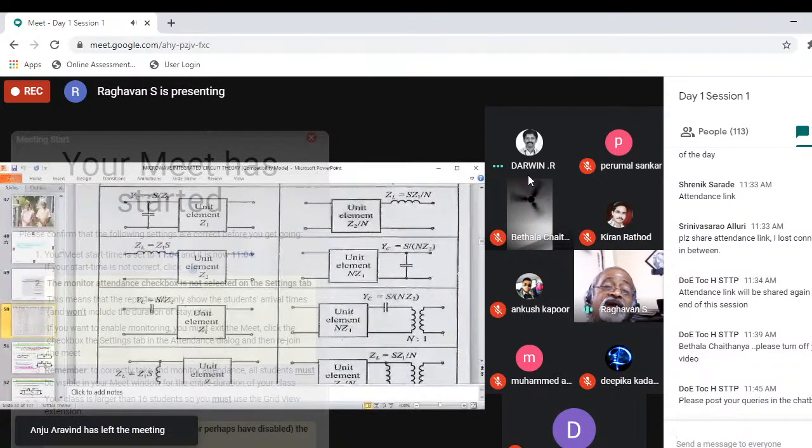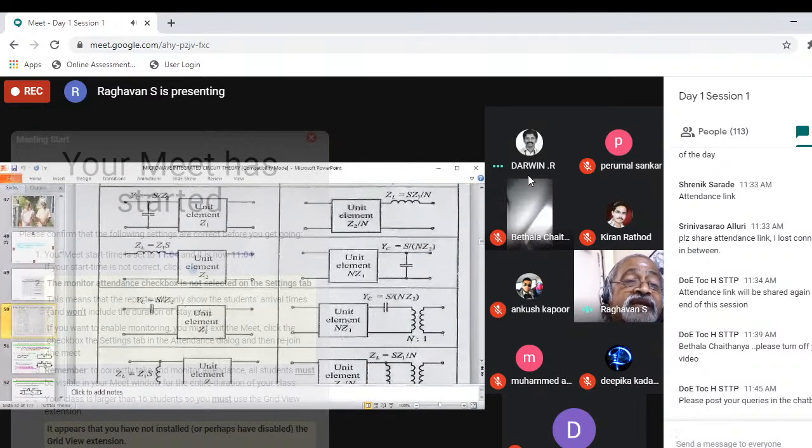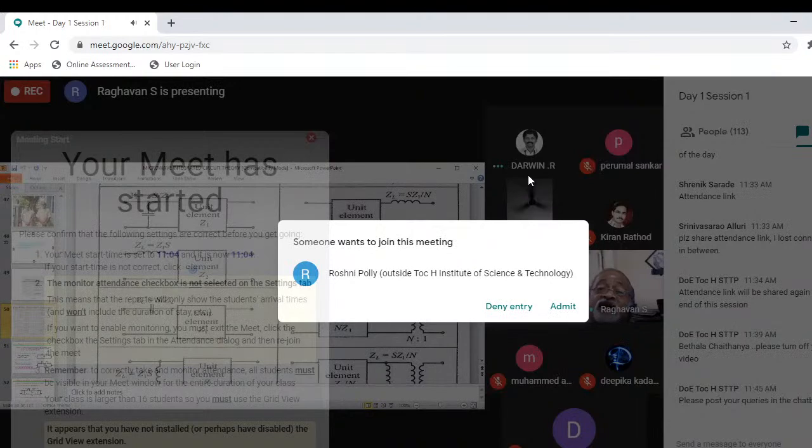To make this Kuroda transformation, you should derive it. How to derive it? On the left side, if you take an admittance, you write its ABCD parameter. You take a unit element, which is also a transmission line with Z0 equal to 1 and length lambda g by 8, and take down its ABCD parameter, find the combination, and equate it.